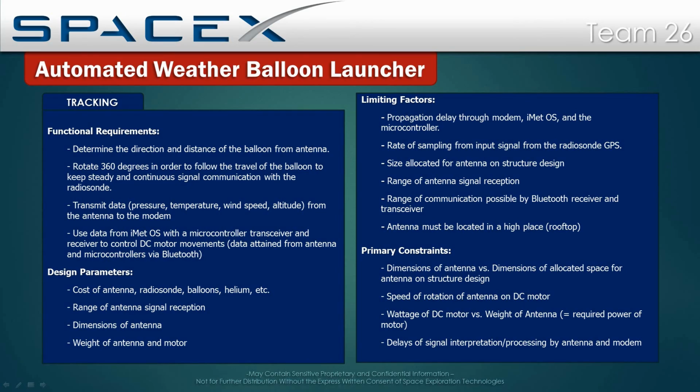This is accomplished by using a Yagi antenna, which will be pointing in the direction of the balloon throughout the balloon's travel. The main challenge of the system is having the antenna accurately follow the balloon. This will be accomplished by creating a structure which will rotate the antenna 360 degrees along the horizon and elevate up to 70 degrees from parallel with the horizon.